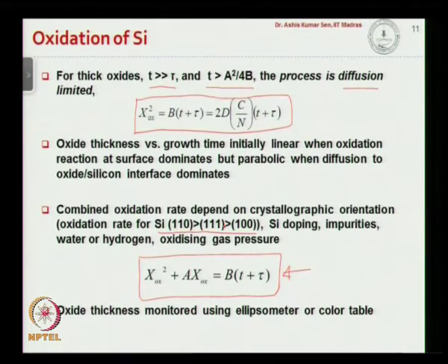The oxidation is also going to be affected by the doping, the impurities that are present on the substrate, water or hydrogen, depending on how we are going to oxidize the wafer, and the gas pressure.